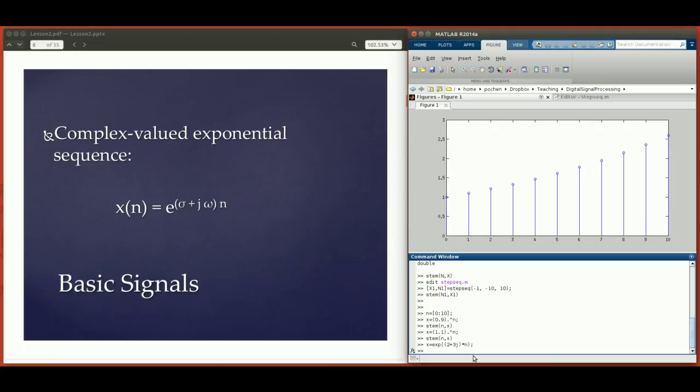I'm going to make a subplot, and in Matlab the command for making a subplot is just called subplot. I'm going to split this figure window into two parts, a left part and a right part. So I want a 1 row, 2 column plot. I'm going to use the first subplot, so it's 1, 2, 1: 1 row, 2 columns, and the first one.